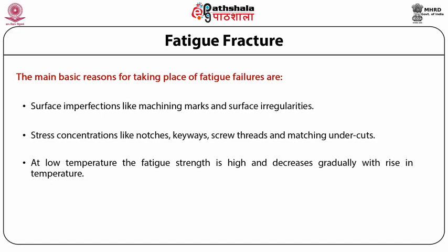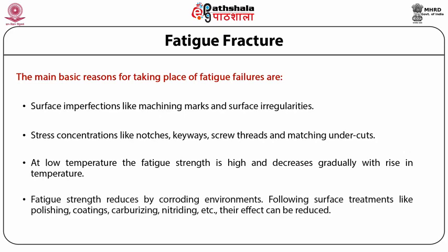And the last reason for fatigue failure is that fatigue strength reduces in corroding environments. Following surface treatments like polishing, coatings, carburizing, nitriding, etc., their effect can be reduced.